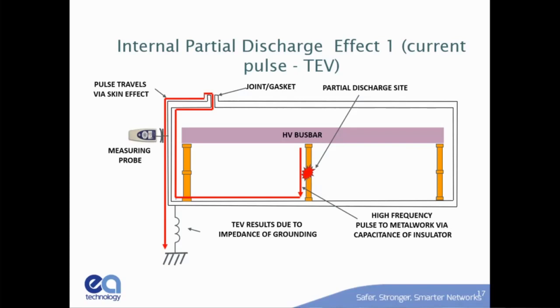So if we go back to Ohm's law and we say I've got a current flowing across an impedance, I have a voltage. And so it's an actual voltage you can measure. And so you have some sort of probe, and the probe is basically a voltmeter. The first lead is a capacitive plate that's built into the front of the equipment. And the second lead is the conductive body of the gear, which you hold in your hand, sort of like holding an AM radio. You get better reception when you hold it. You put it down, the signal goes down. For those of us old enough to remember handheld AM radios, basically it's a voltmeter, and we're just measuring that voltage.